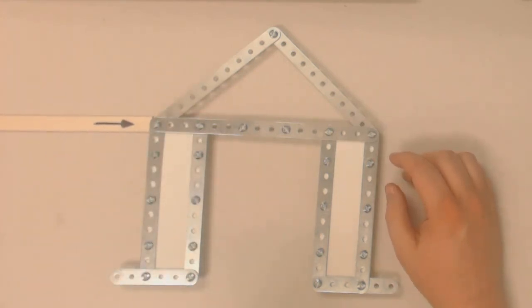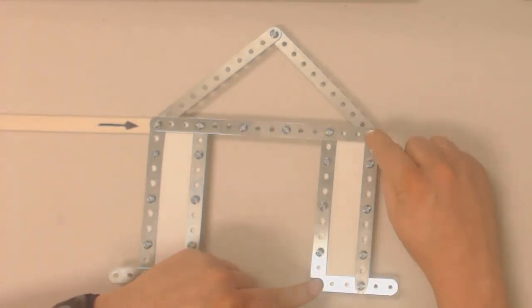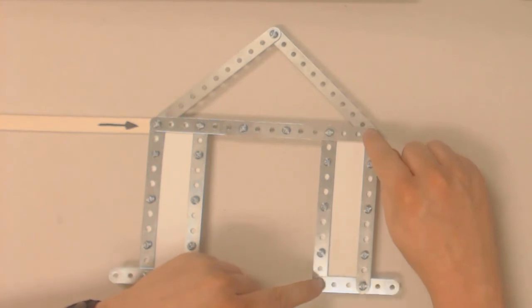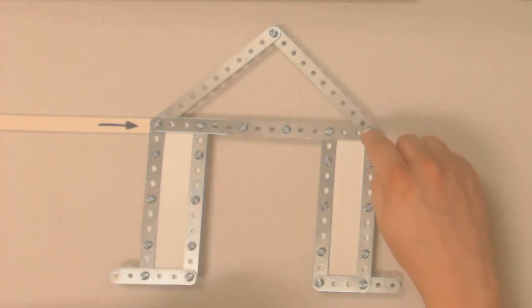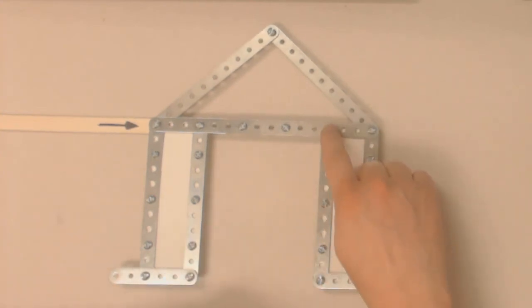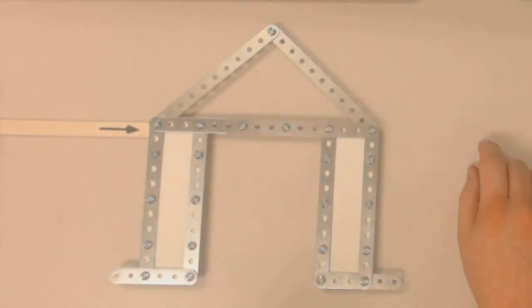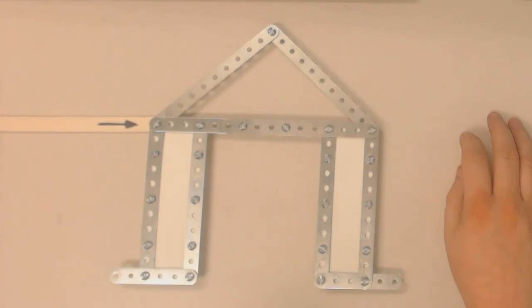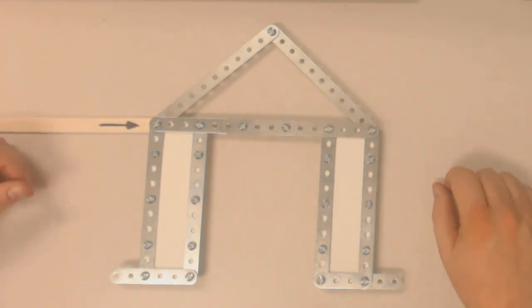What that does is that when the force is applied to the building, instead of only two connections being able to resist that, or two nails or screws or whatever, the force is distributed over, in this case, 1, 2, 3, 4, 5, 6, 7, 8, 9, 10, 20 different screws or nails or whatever. And so that 20,000 pound force, if it's divided between 20 different connections, then each one of those connections only has to account for 1/20th of that force, or 1,000 pounds each. The more connections, the more ability you have to resist that strength.